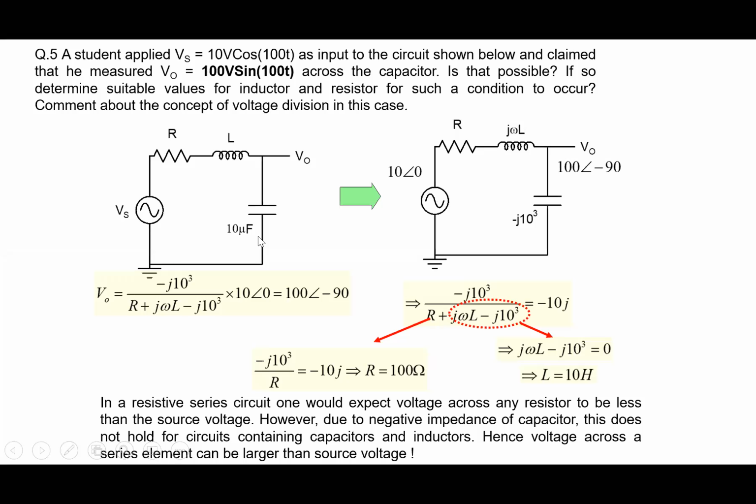This is not an amplifier. The essential condition for amplification is that you should get power gain. There's no power over here. And if you try to extract power by connecting a resistor, let's say across it, you can verify that you will not be able to get a power gain through a circuit like this. So to call something an amplifier requires that there has to be a power gain. And this can never happen in a passive circuit like this.